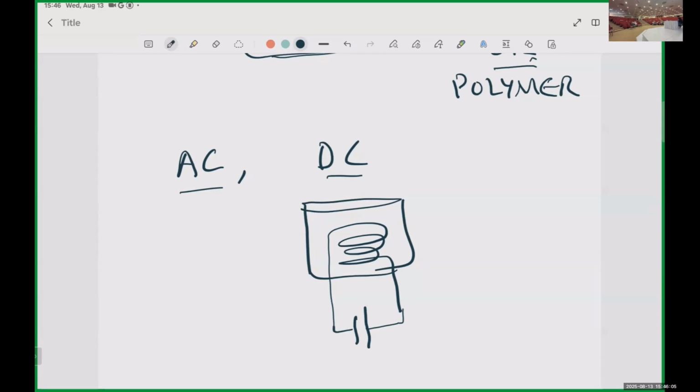But with the passage of time, once they have their own oxidation and etching effect, one leg gets weaker as compared to the other one. It's just like electrodes dipped in a solution. The electrolysis sort of chemistry happens. So one leg gets weaker and weaker and eventually breaks.